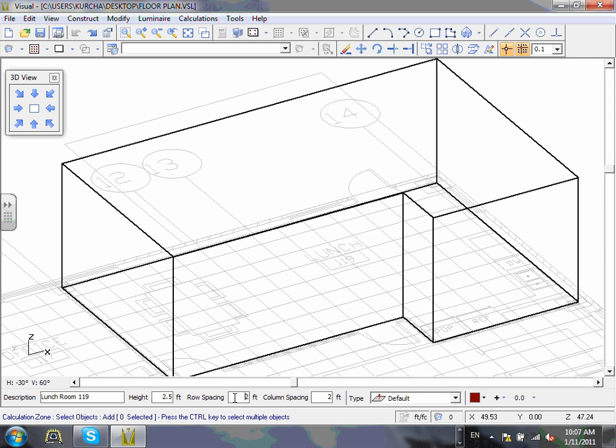Okay, all right, we got that one. Then you still click in here. You still have the square, right? That square. I'm going to pick the floor, and you're going to be very careful picking the floor because sometimes you might not be able to click. I was lucky, I picked the floor. If you pick a window, you have to hit escape. See, it highlighted the floor. Did you guys highlight the floor? If you highlighted by accident one of the other walls, you might have to hit escape out of it and do it again.